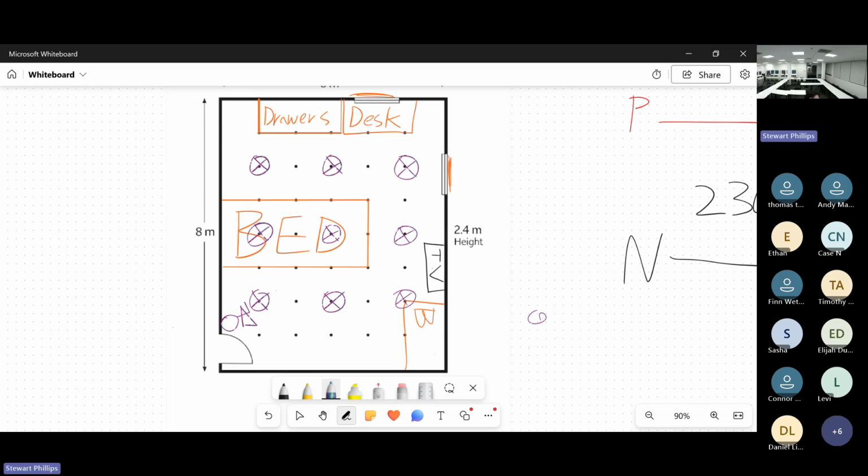So we probably wouldn't use that for a bedroom. We'd probably be looking at 36, which gives off 2.5 meters of light, or probably even less. But the more angle we use, the more light we're going to lose as we get to the edges of the light. And we'll look at this with the inverse square law a bit later on.